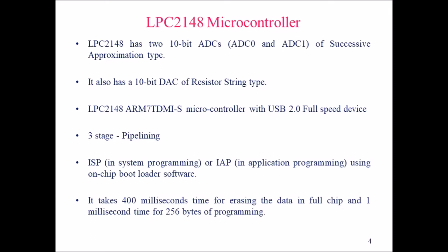This LPC2148 takes 400 milliseconds for erasing the data in the full chip, and 1 millisecond for programming 256 bytes. So the LPC2148 microcontroller takes 400 milliseconds to erase all the data stored on the microcontroller, and it usually takes 1 millisecond to process 256 bytes of data.